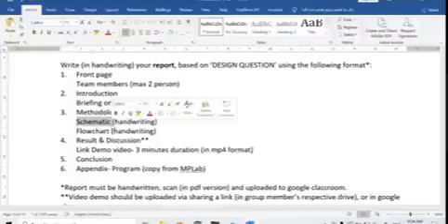Since I already taught you during our lecture, you need to include the circuit for MCLR, the circuit for power supply, and the circuit for clock. That one will be the basic. Even in the exam, everything here must be included: the 3 items, supply, MCLR, and the clock.